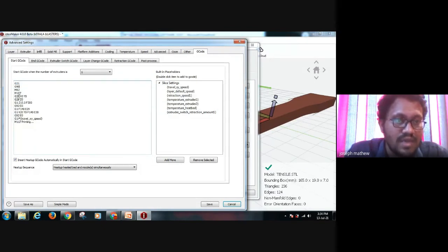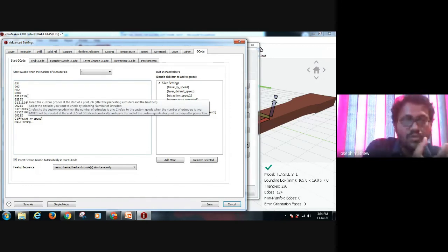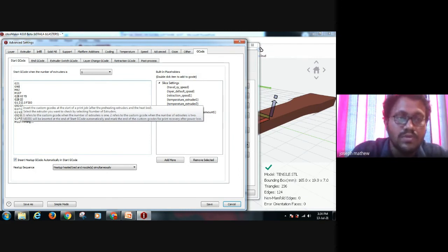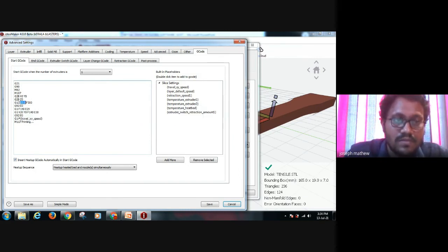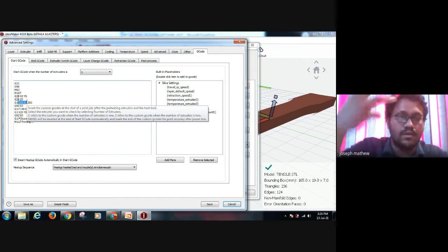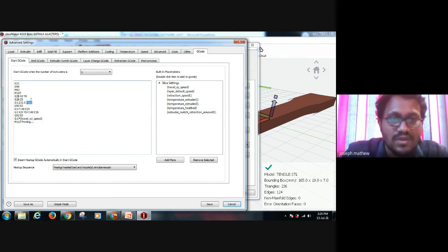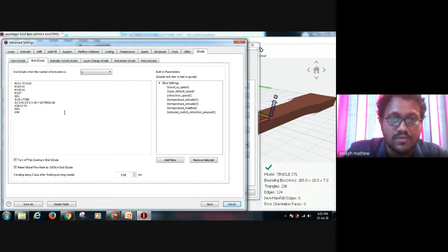The G28 represents the motion of the X, Y and Z axis. So first the G28 X0 Y0. First the X and Y axis go to the home position, that is the 0, and Z goes to the 0. Then the total setup moves to the Z15 position. Like if the printer head is placed at the home position, the printed bed goes down 15 mm at a feed rate of 300. So these are certain G codes available in the start and ending of the process.